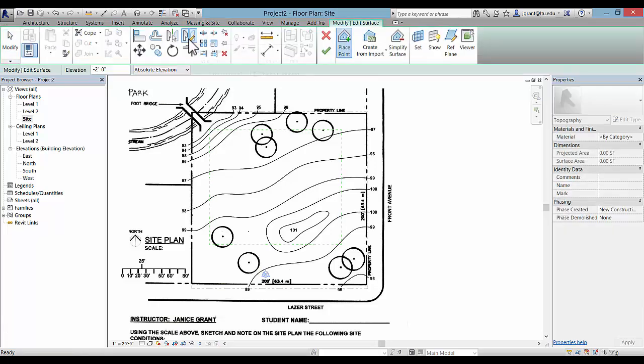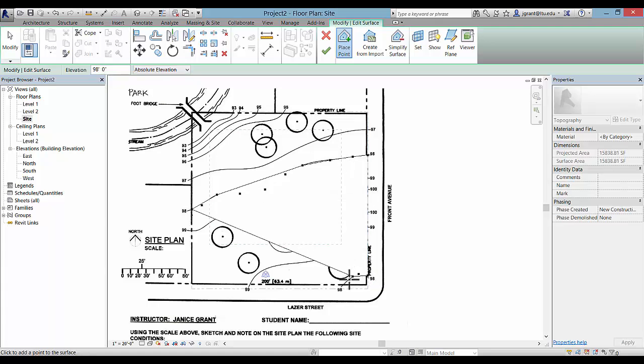click on Topography and change here my elevation to 98. I'll start with this 98 that comes through the site. By placing points, I can start here and start to click on my contour line that's really based on the image. And as you're doing this, you don't have to be exact. And because there's no edge over here, it's okay on this side because all of these end on this side.